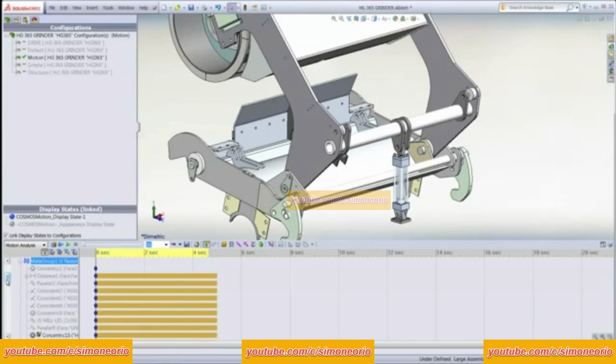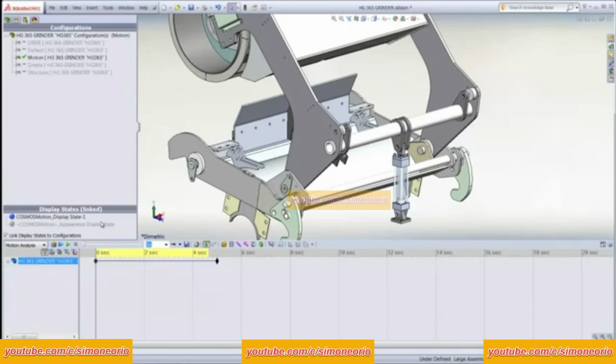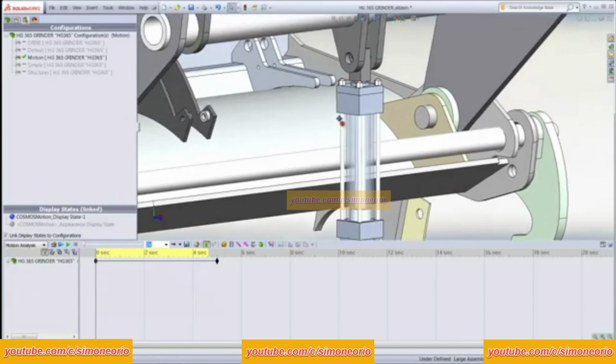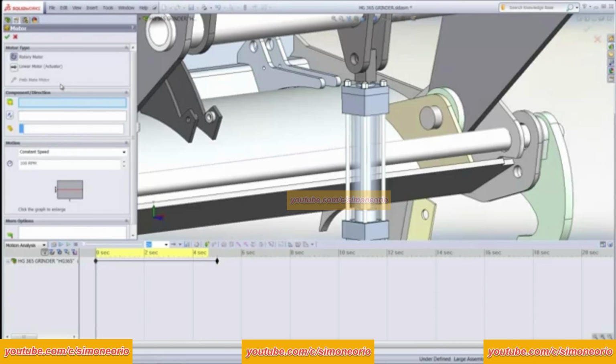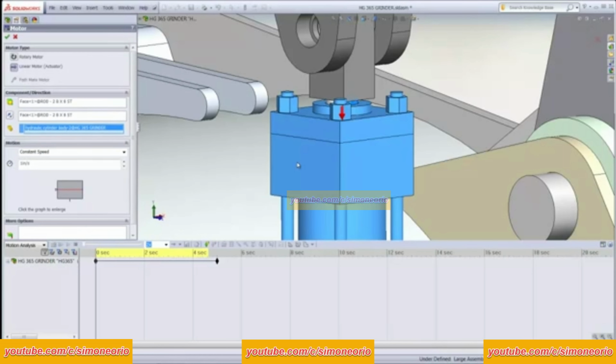Now we just need to control the behavior of the piston, and for this I will apply a motion constraint to the piston relative to the cylinder. Forces and motions can be prescribed using a variety of methods that are easy to apply.